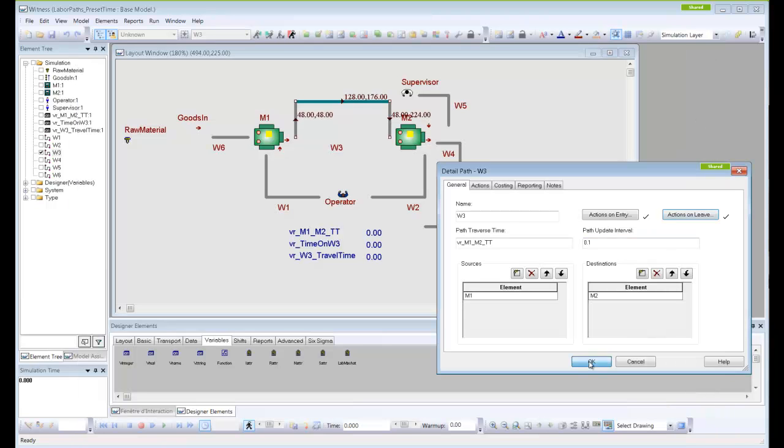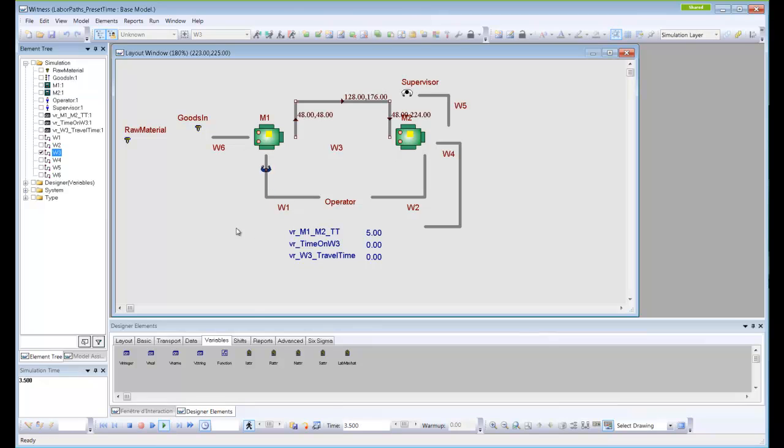So if I set my model running, I can see my labour walking along the path, and I can see the travel time as set in Model Initialize Actions is 5 minutes. Here's a time when the labour and parts commence on the path journey, and this is a time being updated every time our labour and parts leave the path. So in this case I can extend my path length and I can continue running, and I still have the same travel time.